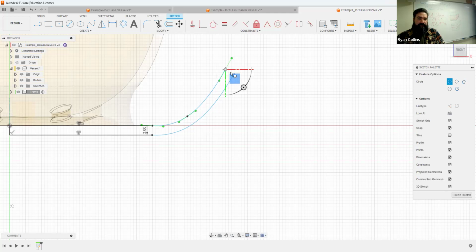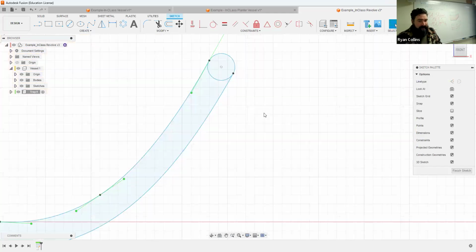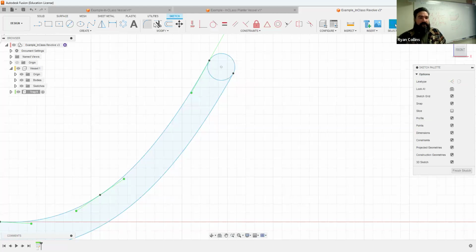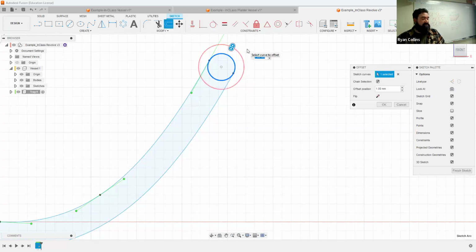And for over here, I'm going to do the same, creating a 2-point circle. There we are. Now, just for the sake of adding stuff, I think it's kind of boring. It's just kind of round. I want to make it more interesting. I'm going to use another circle to make that circle bigger. The reason I'm using a second one is that now I have a center point there. I could have just used a straight line too. It's fine. Make it slightly bigger, or again, use the offset line. Now it's 1 millimeter wider. There you go. That's all.